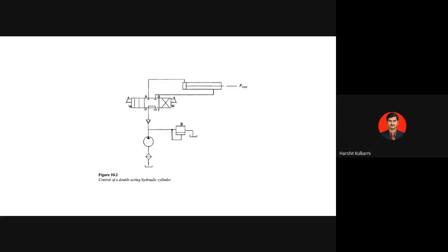Okay. Now come on, let's name this DCV. How do you name this now? Tell me, someone else can try. Name the DCV. Analyze how many ports are there, how many envelopes are there, and what are the control elements for this DCV. Come on, I'm waiting for your answer. Student: 4x3 solenoid spring actuated DC.